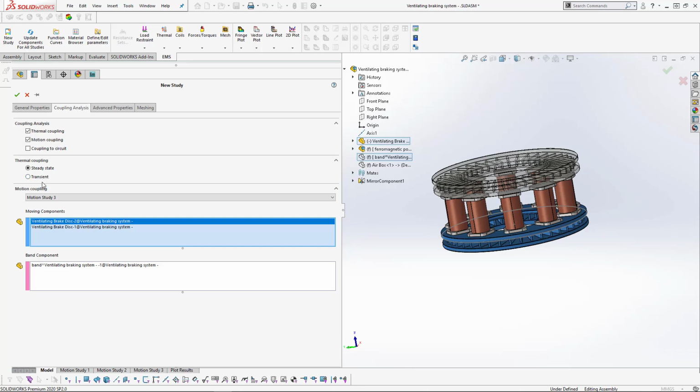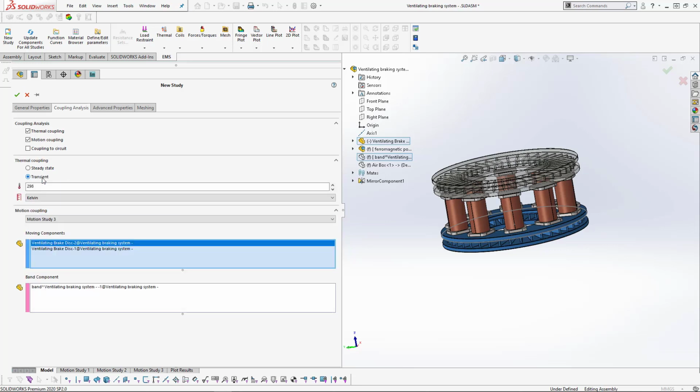We also have the option of transient thermal, so we can do both during the same simulation. We solve both transient thermal and transient magnetic simulation, the magnetic and thermal solutions at the same time. But for this kind of problem, we only solve for, for example, 20 milliseconds, 40 milliseconds, maybe 1 second, and this is not a huge time, so it doesn't allow the thermal simulation to reach the steady state. If we want to reach the steady state, or get some heat, we always want to extend the computation time, so we don't stop at 20 milliseconds, for example, the electromagnetic simulation time.